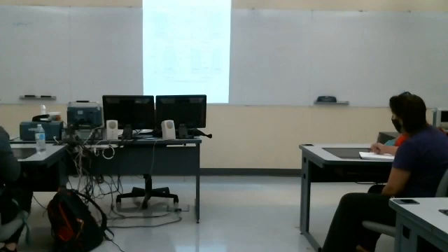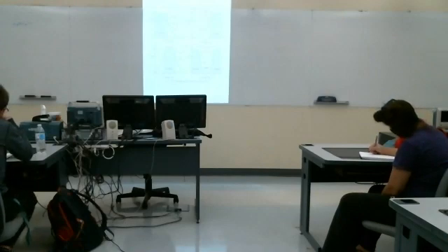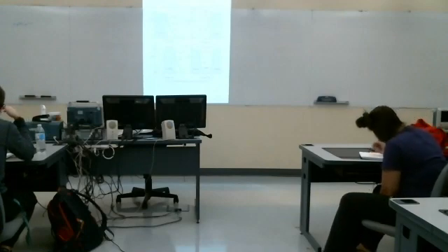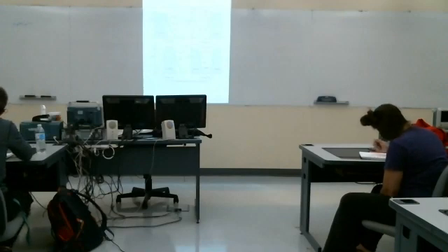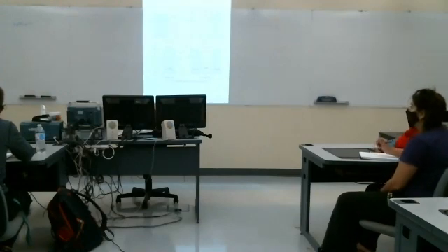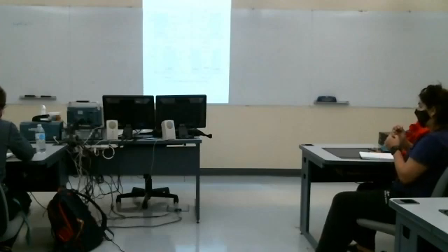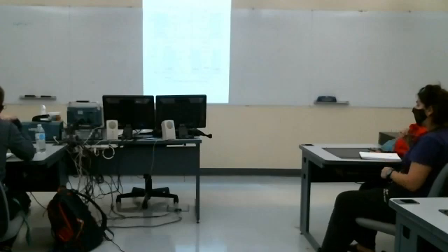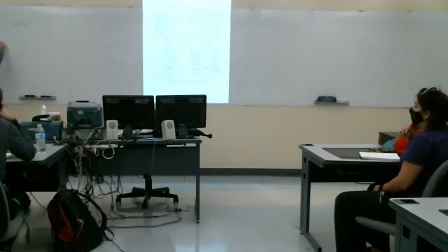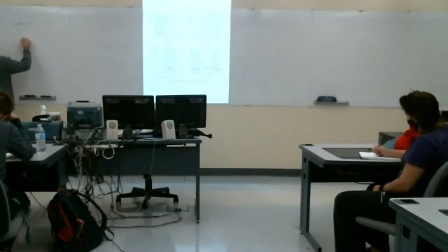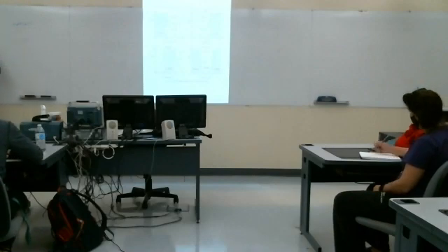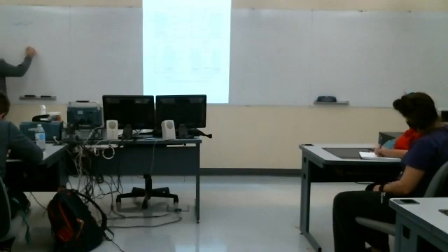You know what the log of 1 is? Log base 10 of 1? The log base 10 of 100? It's the number of zeros in any power of 10, right? So log base 10 of 100 is log base 10 of 10 squared, which is 2. Log base 10 of 10 would be 1. But since we have this multiplication by 20 here, 10 would be 20 dB. 100 would actually be 40 dB. 1 is 0 dB.